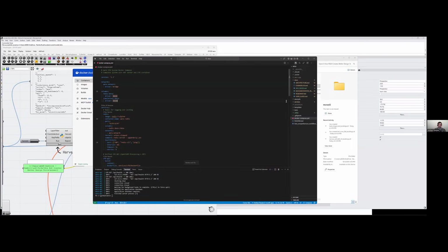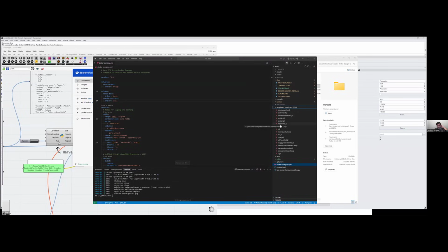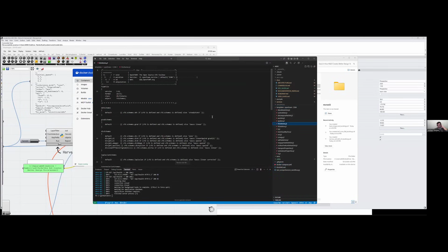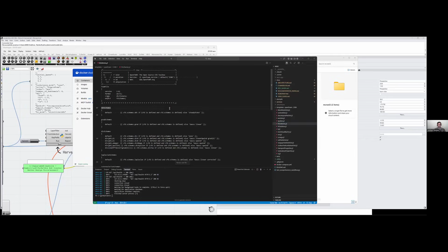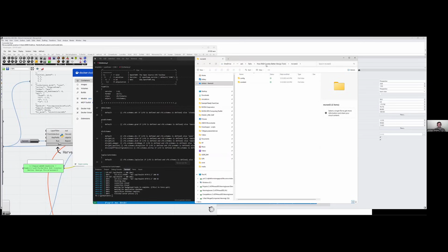And what it does, basically, once I upload it, it goes to what I use in here. It's called Jinja. I have templates for all the dictionaries I need for my simulations, and they're all based on templates that Jinja provides. And I have a script that reads all of those JSON files that you saw and generates these dictionaries in a very specific folder format.